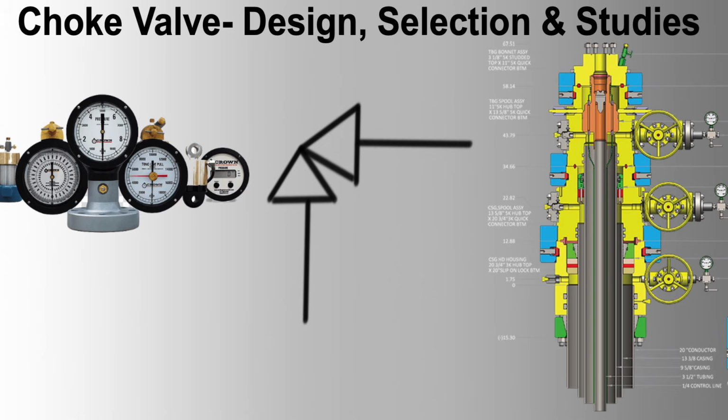5. Fixed choke valves. Example, used in stable flow applications where flow rates do not need frequent adjustment. Advantages: simplicity, simple design with no moving parts, reducing maintenance needs. Reliability, high reliability due to the absence of adjustable components. Cost-effective, lower cost due to the simplicity of the design.